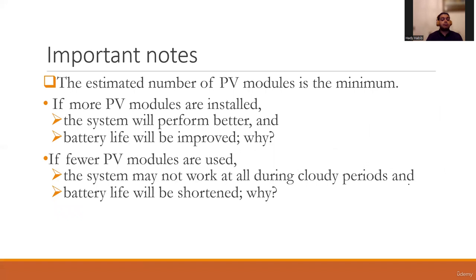The following points are important to follow. The estimated number of PV modules is a minimum. If more PV modules are installed, the system will perform better and the battery life will be improved. Why is this? Because you are not going to use more power from the battery. You are just going to charge it till it's full and it's done. So you are not going to use it much, then the battery will live more time with you, and you are going to increase the lifetime of the battery.